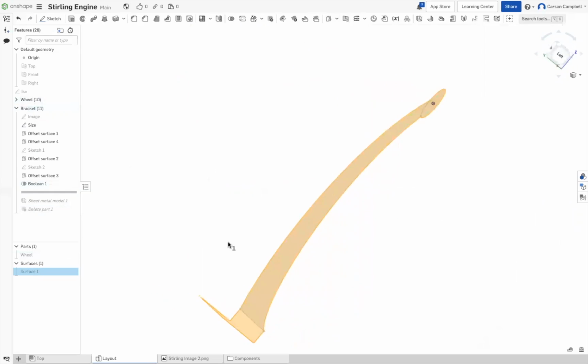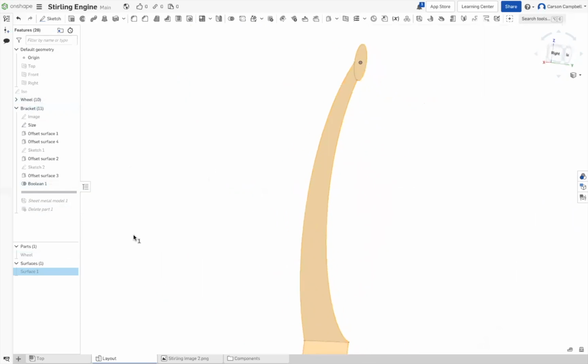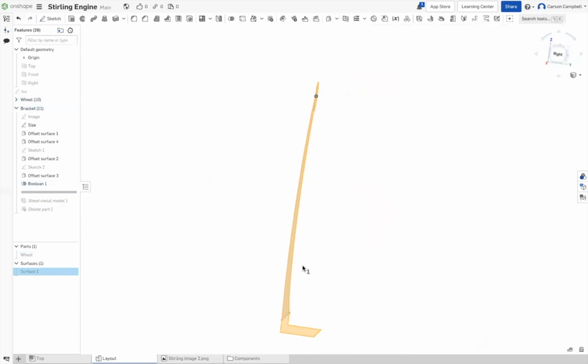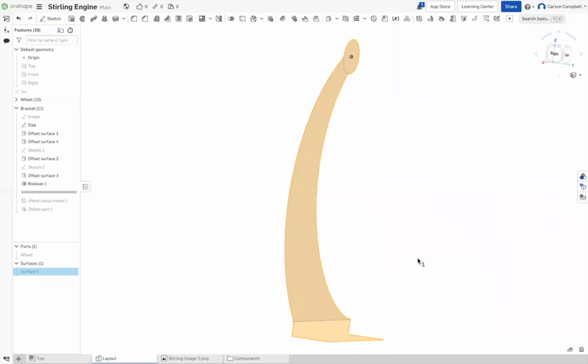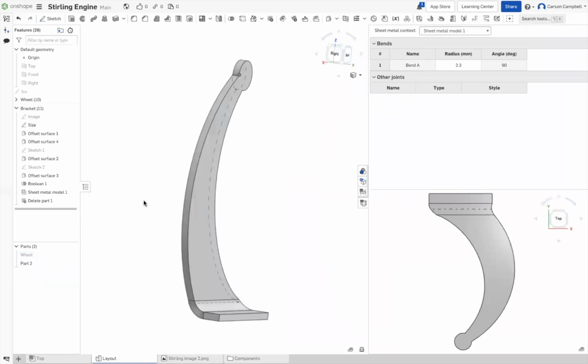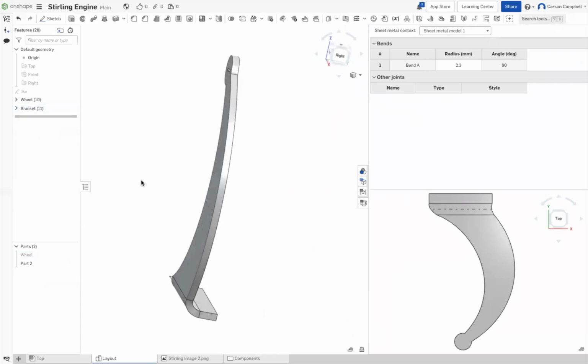It's cool because when you're working with it, you're in the folder, you get your surface geometry. And then when you roll the bar down to the bottom, it's easiest just to right mouse click it and say roll to end. Click on your rollback bar and then shut your folder. Where'd your surface go? You don't want it, not at this point. You already got your part.